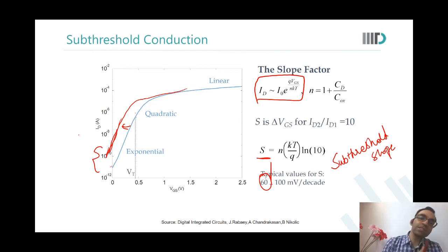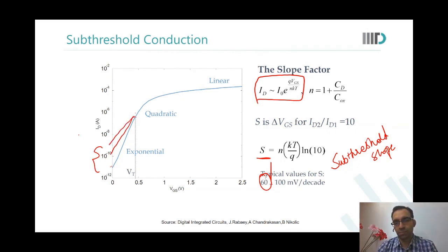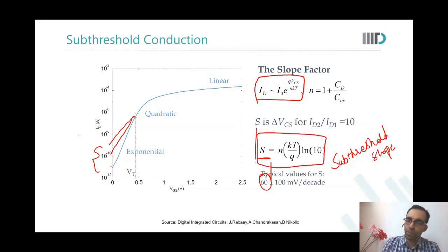Okay. So this is in the same technology. If you reduce VT, this will happen. What I'm saying is, if the technology is bad, then even with the same VT, you can end up having higher leakage. So this I cannot understand. This is a different technology. A technology has a characteristic subthreshold slope.